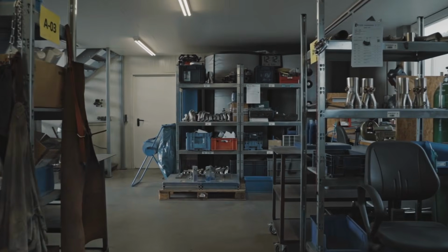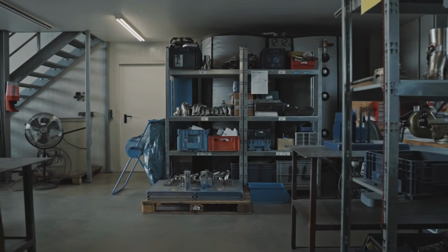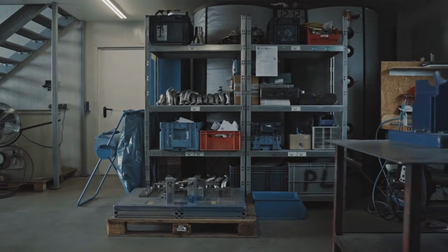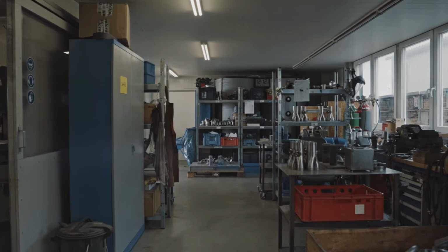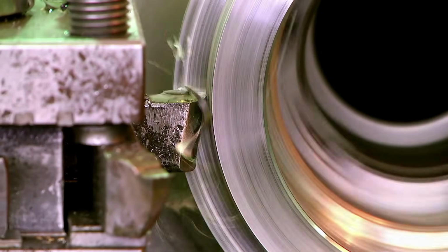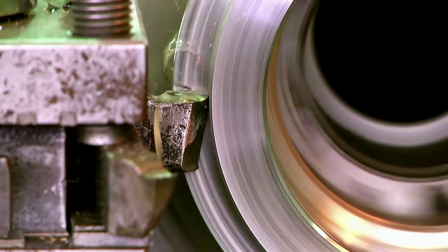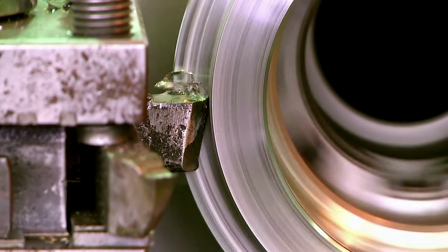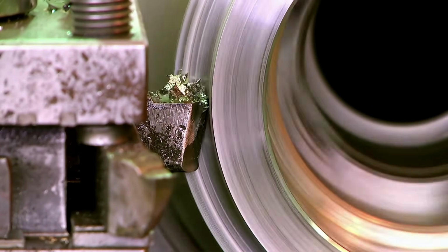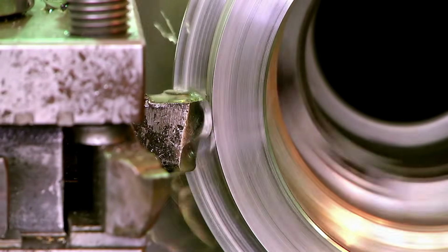And anything close to the axis, small bores, parting, centerline finishing: G97. Pick an RPM that gives reasonable surface speed at the average diameter and live with it. Everywhere else, OD turning, facing on big stock, roughing, G96 wins. Better finish, even tool load, consistent chip, just cap it with G50.